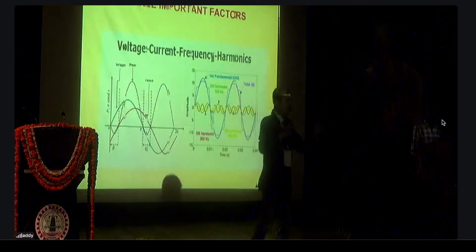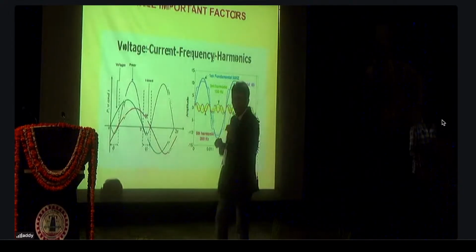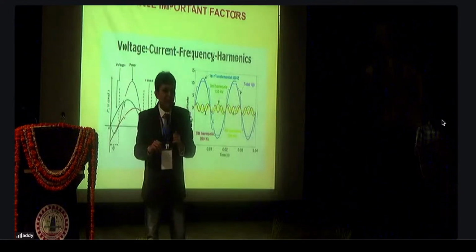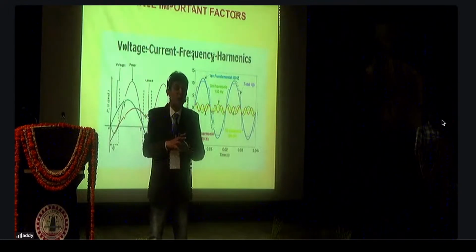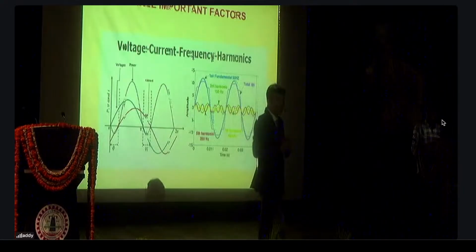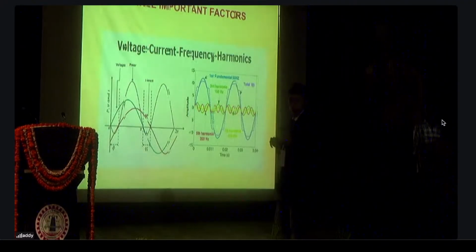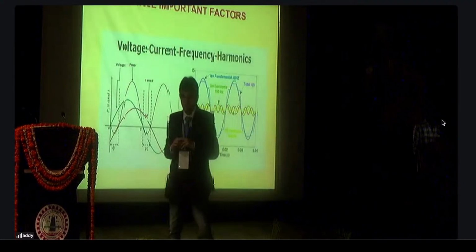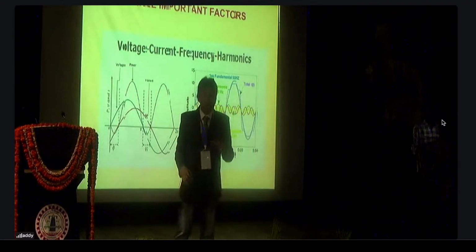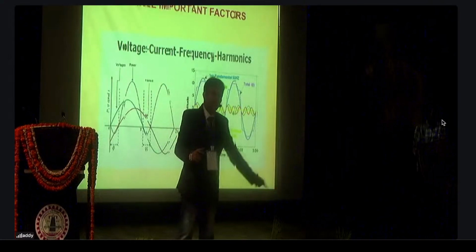And the solutions lies in only three fundamentals. Only three. These are basic of electrical engineering. It is your voltage. When I say the quality of voltage, that depends on the insulation level you provide, that is called BIL. Then comes the current. You have to ensure the quality against the overloading short circuit capability of your system. And last but not the least, frequency. When I say frequency, you have to ensure that whatever gadgets you have don't inject harmonics into the system.